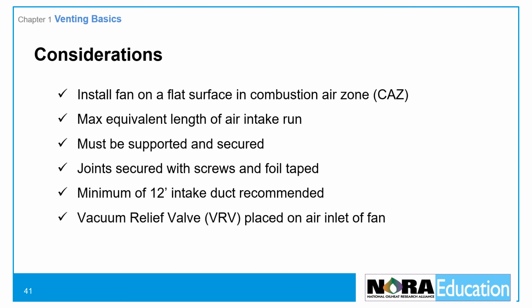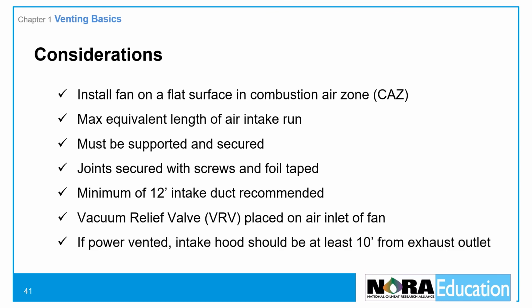A vacuum relief valve should be placed directly on the air inlet of the fan unit, and if the heating appliance is power vented, the intake hood should be at least 10 feet from the exhaust outlet and on the same wall of the building.